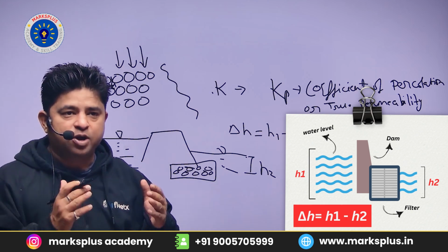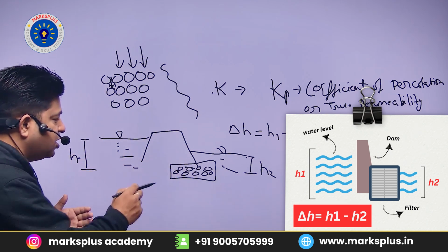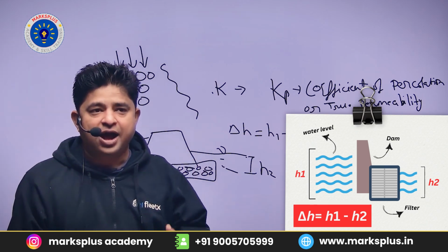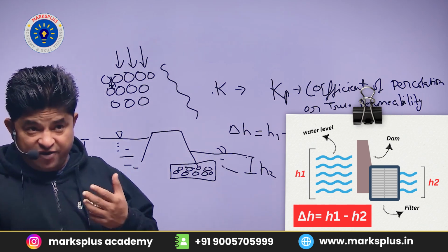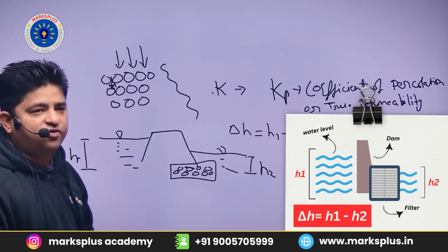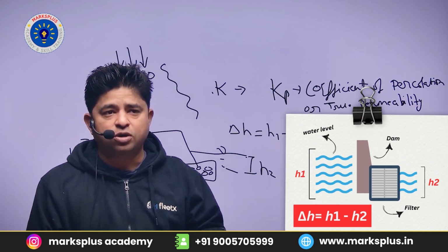Okay, and when the water flows, why is it important to design a drainage filter? Because of the head difference, if we do not control it, the pressure at the lower end will be higher and it may cause a failure of the dam. That is why it is very important to design a filter.